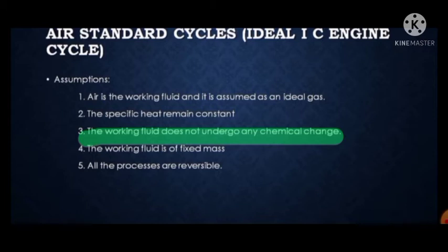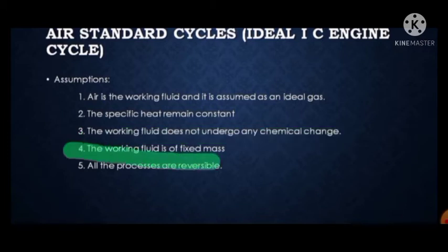Fourth, the working fluid is of fixed mass. In an IC engine we will take it as a closed system process. There is an inlet valve as well as an exhaust valve, so it is actually an open system. But to make the IC engine concept easy to understand, we are taking it as a closed system. The working fluid is of fixed mass. I have already explained in my thermodynamics lesson that fixed mass is a closed system and an enclosed volume is an open system. So we are considering it as fixed mass, that is, a closed system.